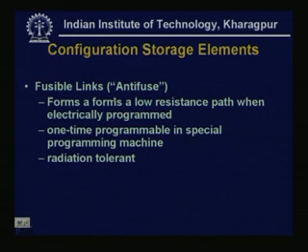Now, configuration storage elements can be fusible links. Already we discussed that fuse or anti-fuse is used to turn the cross points on or off. It forms a low resistance path when electrically programmed, is one time programmable in a special programming machine, and this should be radiation tolerant.